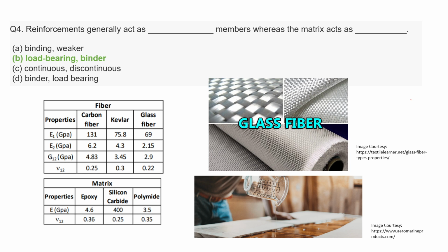There are normal fabrics also, normal fabric mats, chopped strand mats and everything. So there are different forms of reinforcements. These reinforcements got combined with our polymer, and that made the whole composite with properties comparable to the other initial materials we used, metals and ceramics. As I said, when these reinforcements came into the picture, only then did the strength increase.